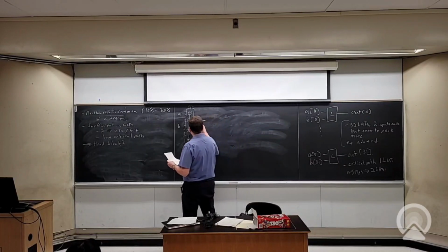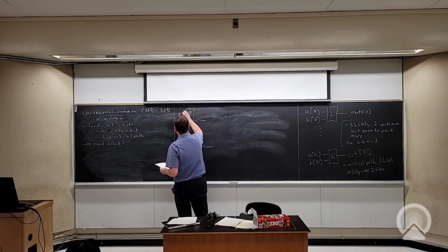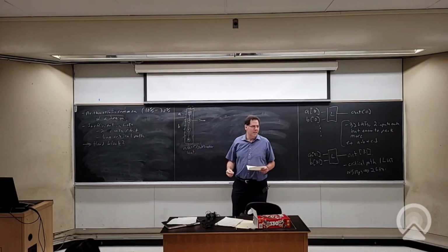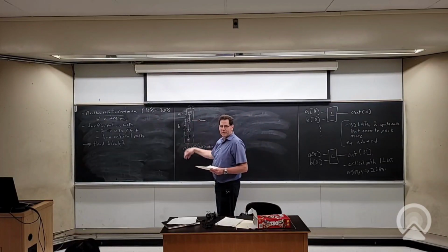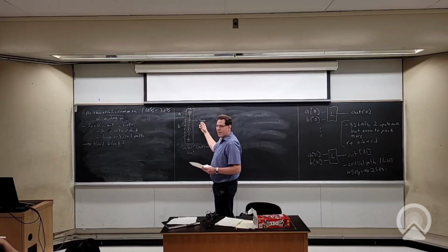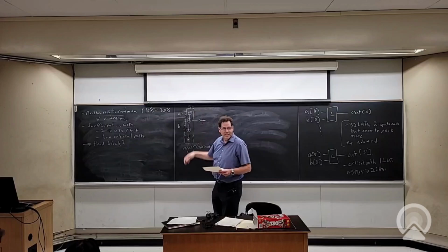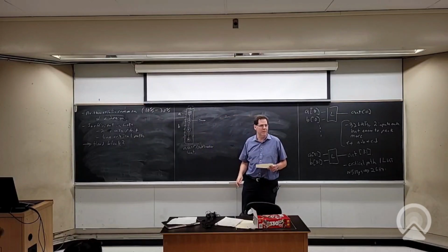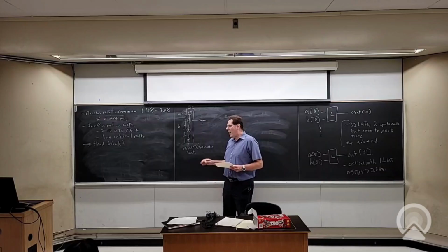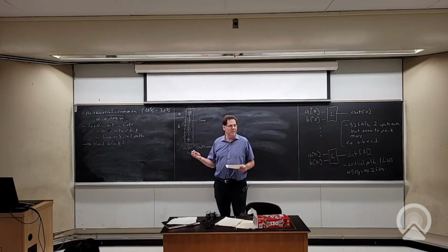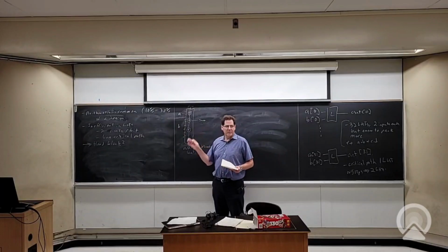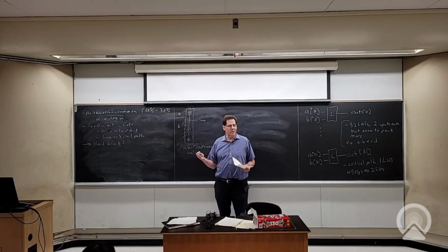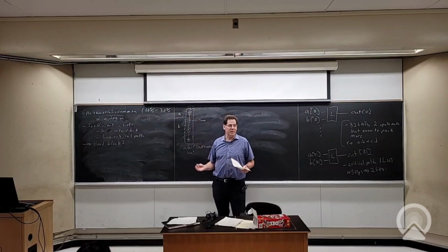There's also, is this cheap? These adders are really cheap. What about these? How many inputs do I have? I got 32 inputs. I got 16 full adders, and I got 16 outputs. Well, and another couple, so I've got maybe 17 outputs and 33 inputs. How expensive is it for me to build all those routing ports? That's on the order of how many inputs and outputs I have for a logic block. So from a routing perspective, this thing is close to the cost of a logic block. From the perspective of what I put inside it, it's a tiny fraction.